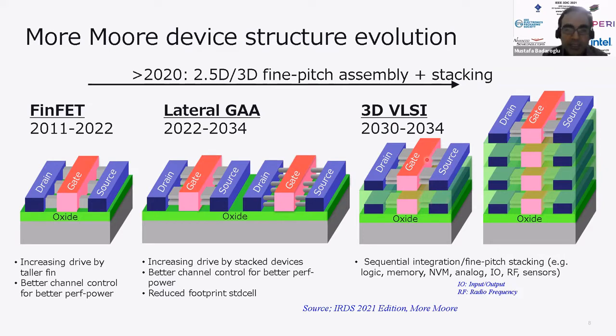That will be defining these technologies, but they will always be based on the baseline gate-all-around device. And then more stacking generations with true 3D heterogeneous integration, for instance different wafer substrates, might appear in the second generation of 3D, which is defining a full true 3D system in the cube.